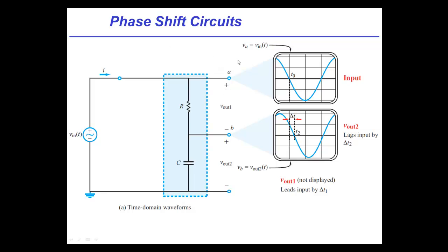You saw that in that last example on phasor analysis that we did in the previous module, which we encourage you to review if you don't remember, that we can use complex impedances to shift individual voltages within a particular circuit. Now what that means is it's possible for us to take circuits that we have, such as this one here, which is a voltage source driving a resistor and capacitor, and cause a phase shift in individual voltages.